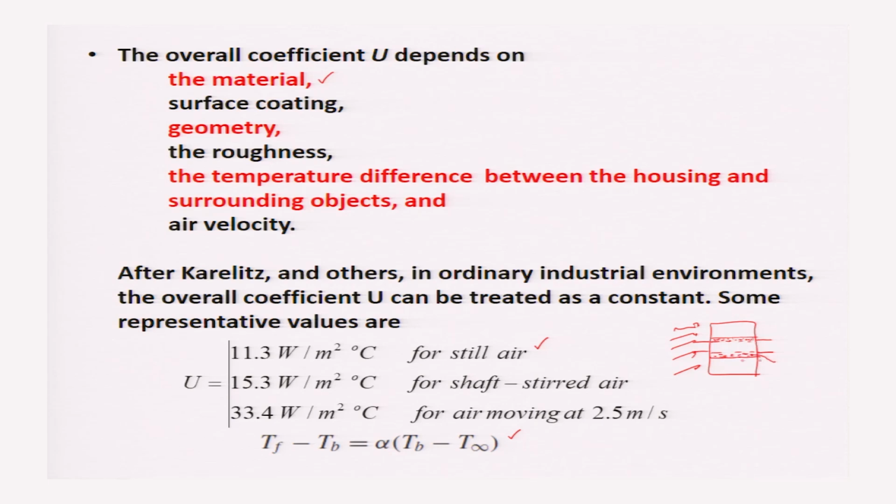So, the lubricant temperature is represented as Tf, and this is the required temperature because this temperature must be known because it will affect the viscosity of the lubricant, and from this temperature and the rise in temperature we will get the viscosity, and thus we will get the Sommerfeld number. So, this Tf, the fluid temperature, is an important term.